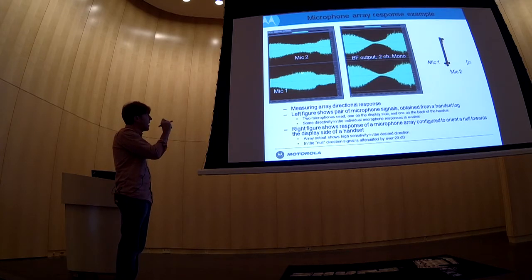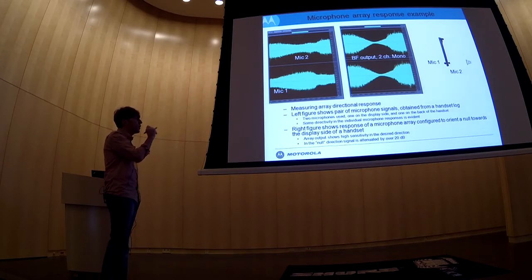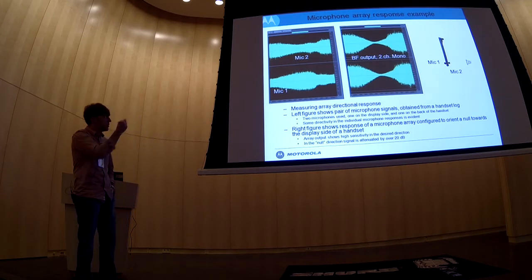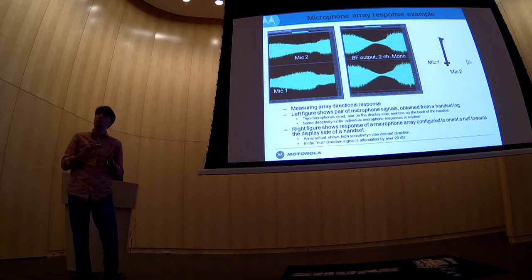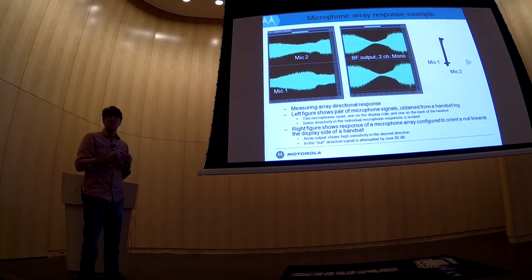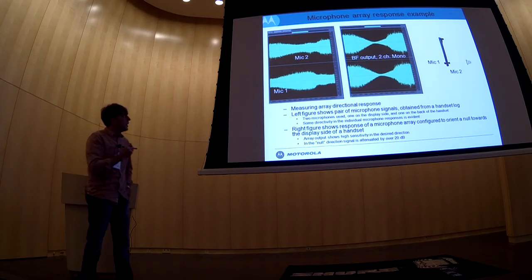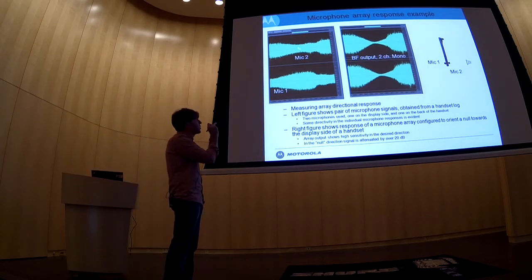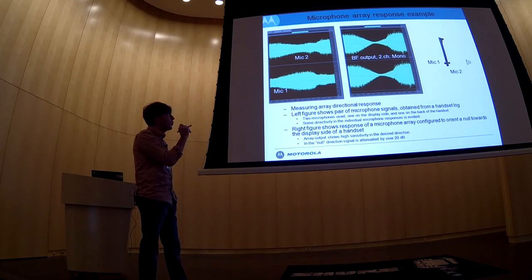Consequently, microphone 1 is able to see a lot more signal in that place. The actual directivity that we get out of the microphone 1 and 2 signals is on the order of 4, 4.5 dB. It's obviously band limited and frequency dependent. Those two signals are then combined, and we are producing a differential array with the following output.